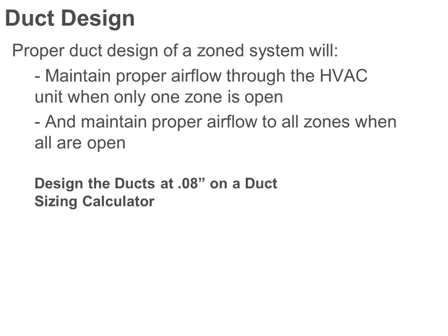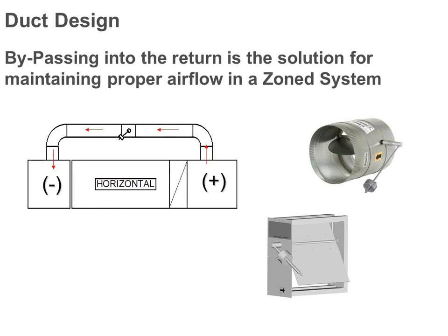All right, in terms of the bypass, its job in life is to steal air out of the supply duct and dump it back into the return duct. This is not an energy saving thing, right? So we want to avoid it as much as possible. However, as zone dampers are throttling back, we have to shove the air somewhere. We can't shove 1,000 CFM through a 6-inch damper. It's just going to be too loud and too problematic.